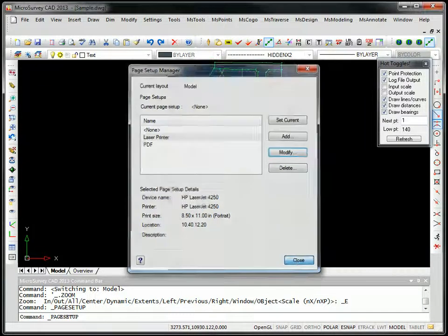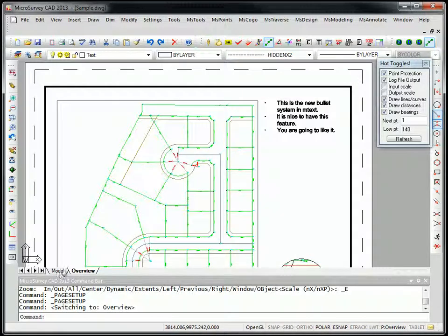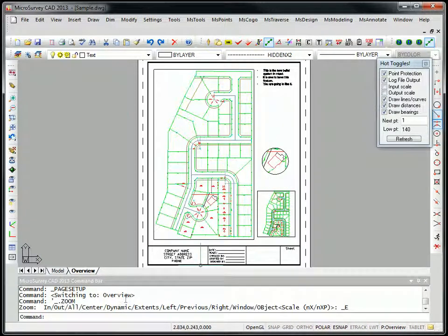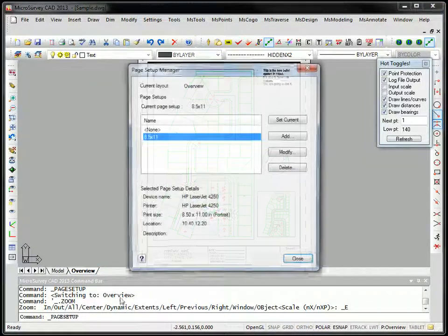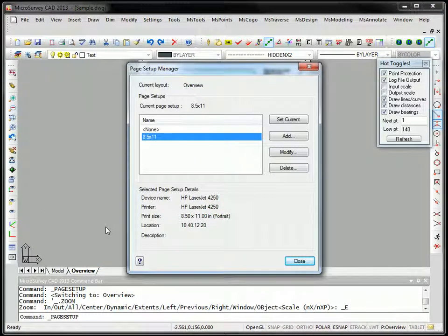And you can also set up for your paper space views. You're going to see in here too there's some improvements where you got this background here of your sheet size, so you can visually just see how your viewports and your objects are going to fit on that sheet and title block that in this example that I've got inserted. And again, you can right click on your layout tab and go to the page setup manager, and here's some configurations that I got set up for my paper space views.